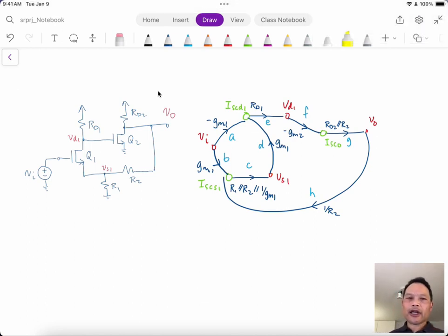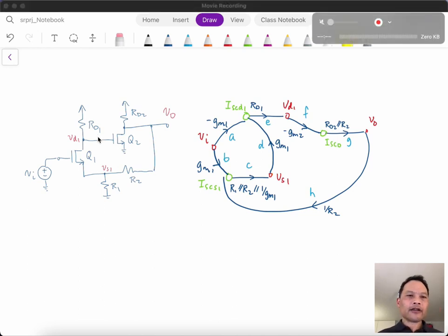That includes taking the schematic from SPICE and then automatically generating the signal flow graph, the ability to toggle between the symbolic expressions and the numeric values, the ability to determine expressions for the loop gain, as well as to plot the loop gain as a Bode plot, and the ability to change values in order to see how the values affect the loop gain and stability properties.